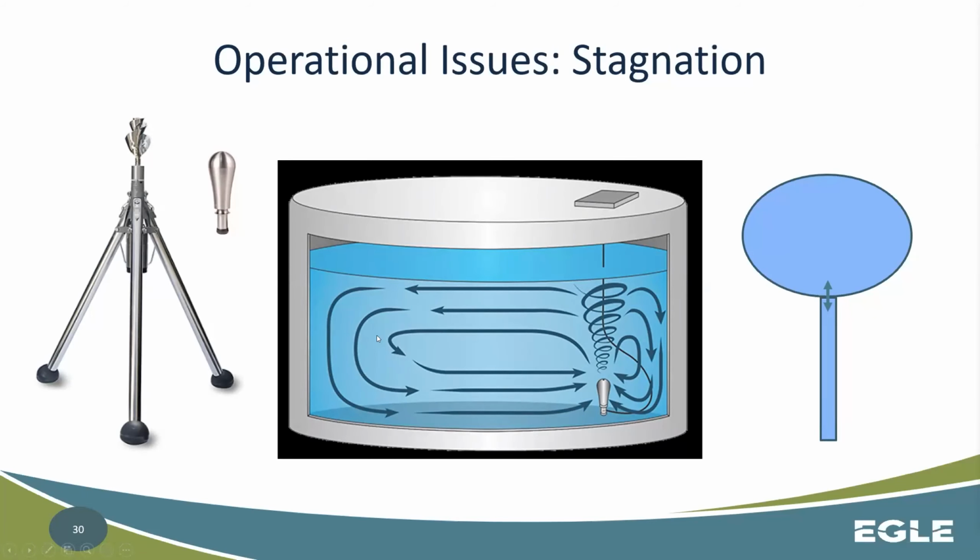It's just getting this portion, but it's not touching this whole second half of the tank maybe. So getting diffusers and mixers in there, stirring that up, getting turbulent flow into the tank, that's getting it mixed together and then getting a more consistent output.